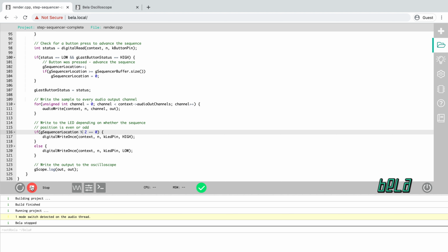You might have heard a couple skips in there, where pressing the button seemed to jump a step. The reason for that actually has nothing to do with our code and everything to do with the mechanics of the button. The metal contacts on the button are spring-loaded, and like any spring, it literally bounces. We'll talk about debouncing buttons in a later lecture.